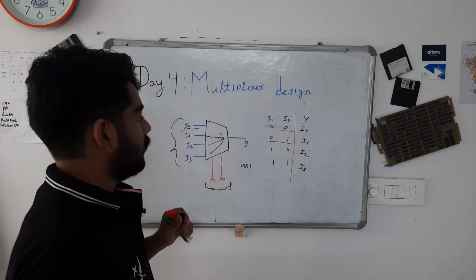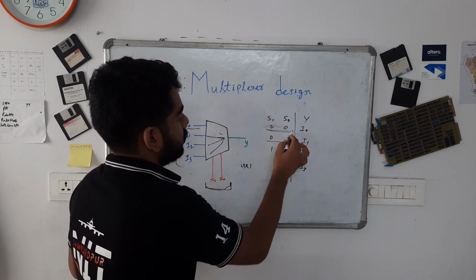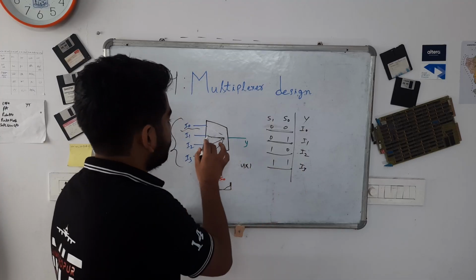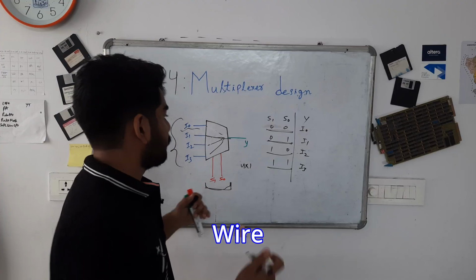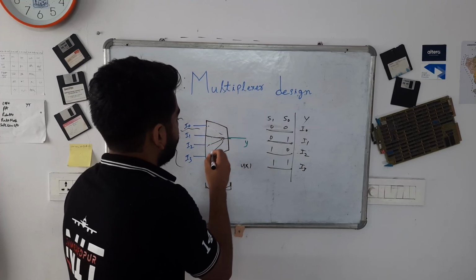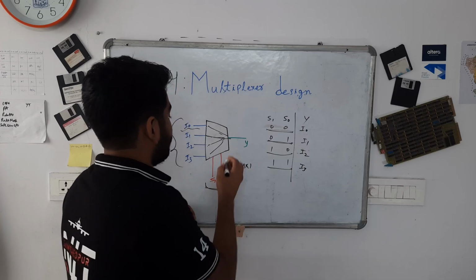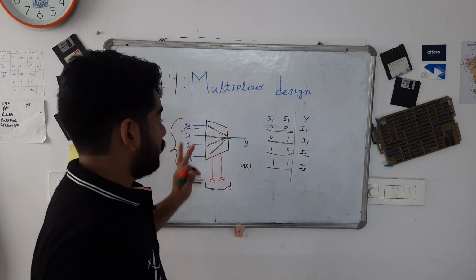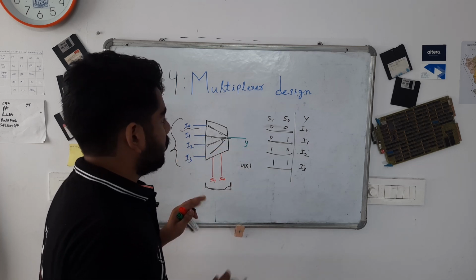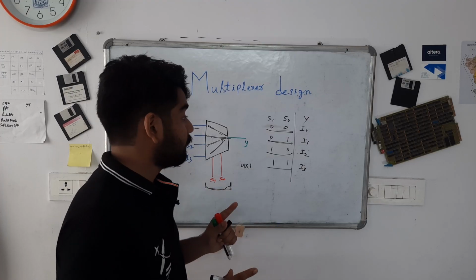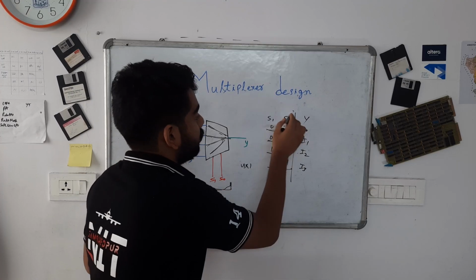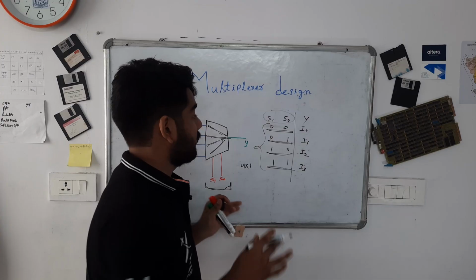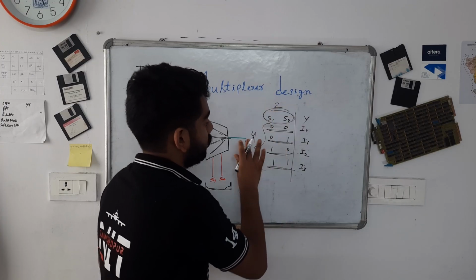similarly here, right? So as you can see, we are selecting which input to pass on to the output. Think of it as like a wire. You have pins over here, and you are connecting wires between the input and output, and depending on the command you connect different wires. So this is how it works, and based on the number of selection lines, the input lines will increase or decrease, right? When you have two selection lines, you can only represent four different combinations. There is no other combination possible. Two selection lines made four combinations.